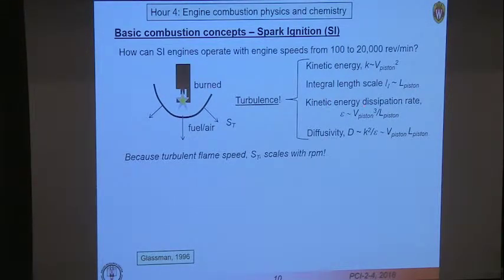The energy dissipation rate you can get by looking at the time scales is then, as this formula shows, and the diffusivity, which is the kinetic energy squared over its dissipation rate, comes out to look like a velocity times a length scale, which, by the way, is almost the same as what you would have got from kinetic theory, except that here this velocity is the speed of molecule movement, and L is the time between collisions. So there's a similarity in the way that quantities are diffused or transported in the argument for turbulence, that the velocity and the length scale are the important parameters.